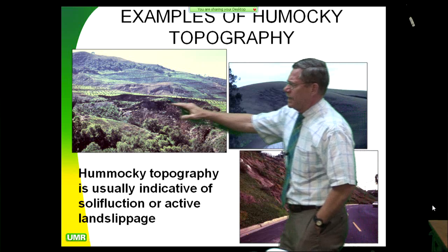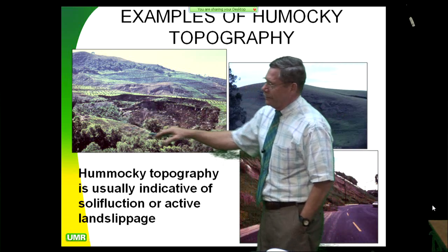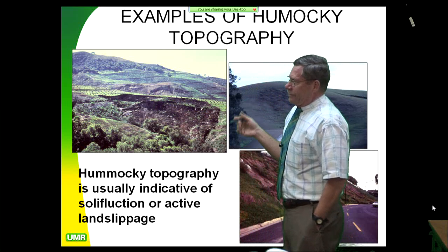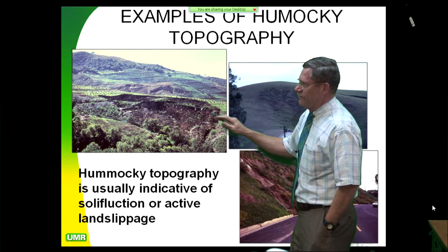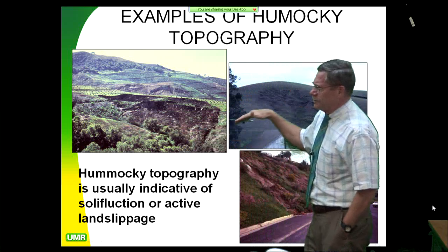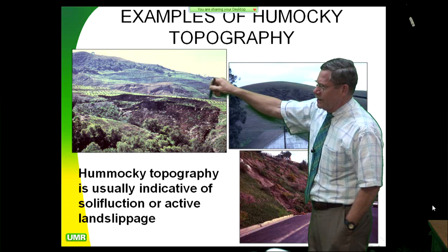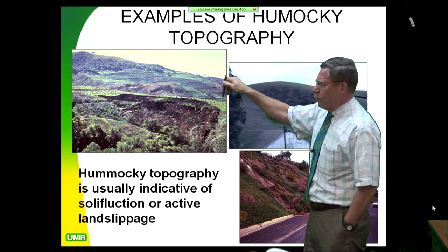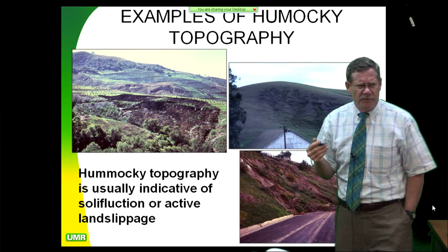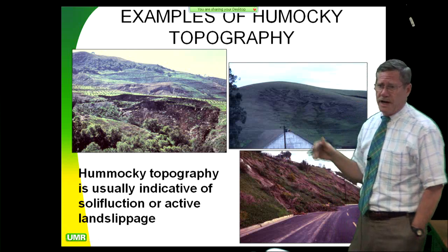So here's a big landslide. This is down in the Santa Paula Valley, Santa Clara River, down near Santa Paula, near Ventura, California. And we're looking at here, these are orchards, and these are avocado trees. These are full-grown trees. So this is a very large slide we're looking at here. There's a big thrust fault underneath it, and they're watering every one of these trees. They came in, graded this old slide off, not realizing it was a slide, started watering the trees, and they got to give them about 44 inches of water a year to get them through the dry season in California